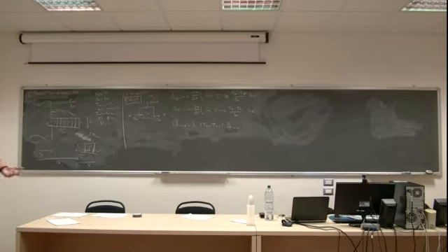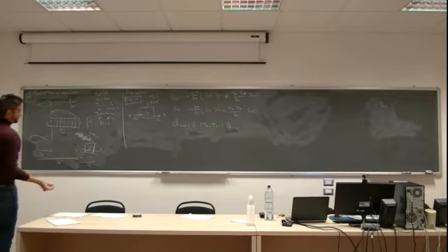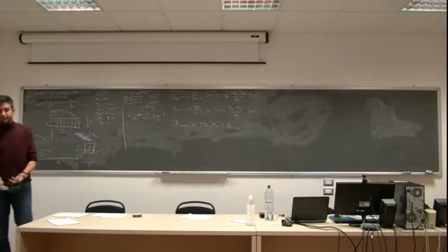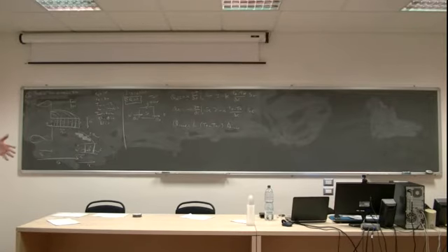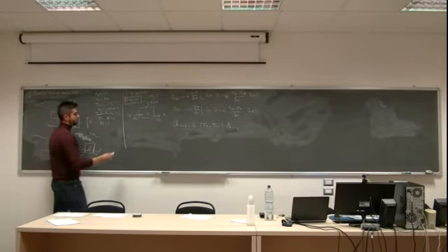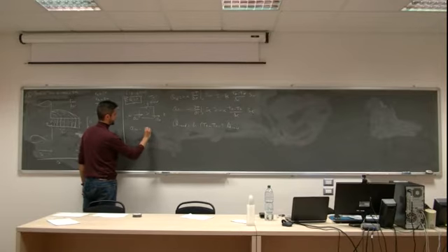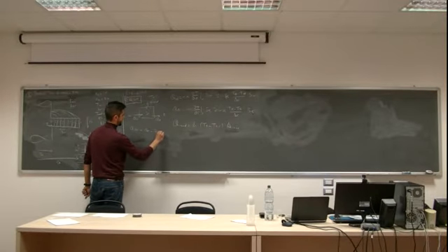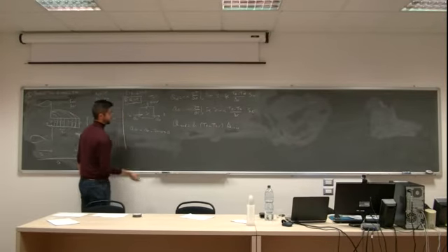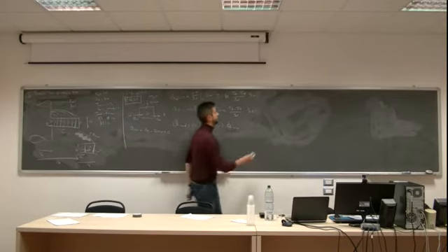Because we are in a steady state, there's no accumulation of energy. So all the energy going inside the node has to be released by the node. Everything in, everything out. So what is in? Q west minus Q east minus Q convection is equal to 0. Okay, let's go here.